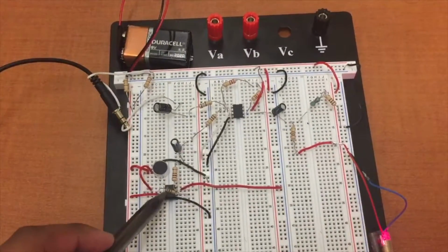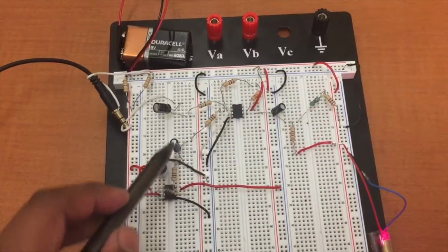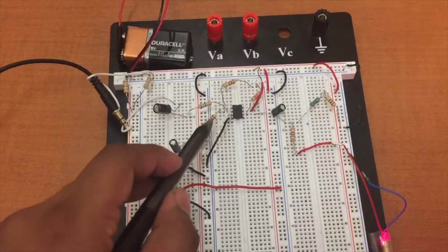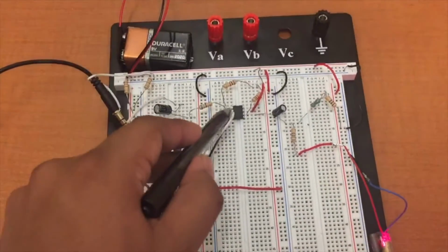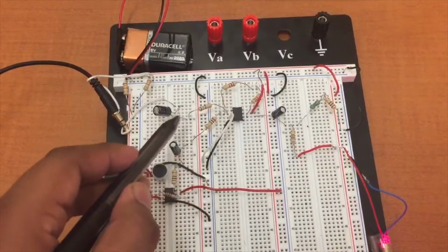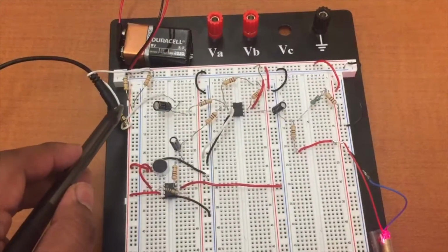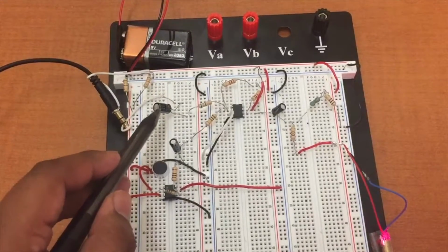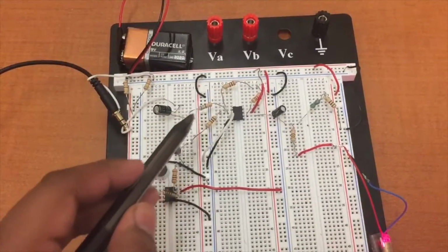So as we continue on, the op amp is connected to a 10 ohm resistor, which is connected to a 10 microfarad capacitor, and goes to another 10 ohm resistor. And we have this node right here where one end is coming from the op amp, and the other end is coming from the phone, and the phone's connected through this aux cord that's connected to the 0.47 microfarad capacitor and a 680 ohm resistor.